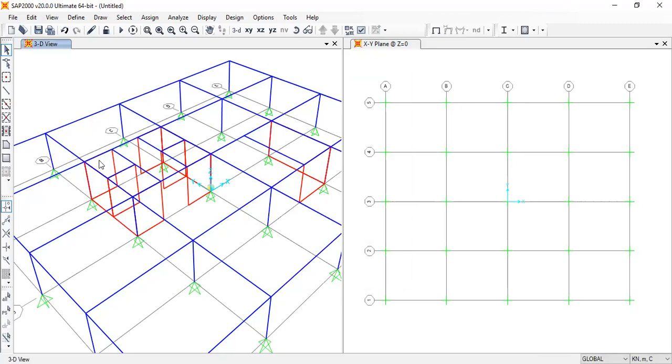Now it's done, right? So I'd like to have these beams. The reason is if you have these beams, you can transfer these loads to this wall very well, right? Rather than connecting by using area elements. From the finite element viewpoint, if you have area elements, they are only connected at 4 nodes, right? If you want to connect it at each location, what you have to do is simply mesh it, because the points where you mesh define the matrix, right?